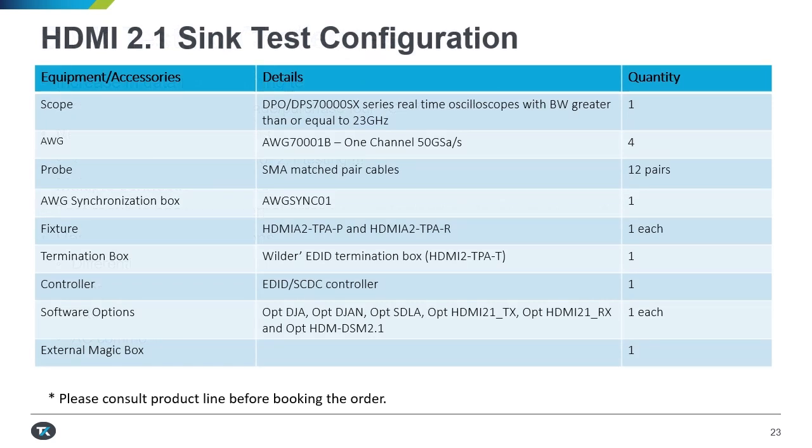The sync testing requires a source which is capable of generating a wide range of test patterns and the ability to add a precise amount of impairments to the output signal. Jitter tolerance, skew, sensitivity, and timing testing with repeatability are critical. For customers who want to reduce test time with the performance to meet the new standard requirements, Tektronix offers a complete test solution for HDMI 2.1 sync testing. The Tektronix sync test provides an end-to-end automated solution with significant reduction in test times.